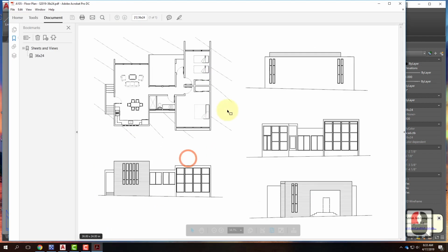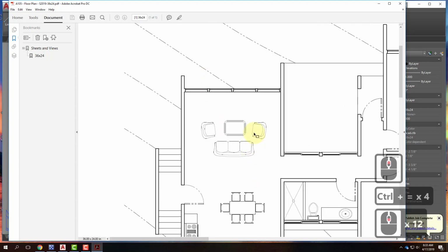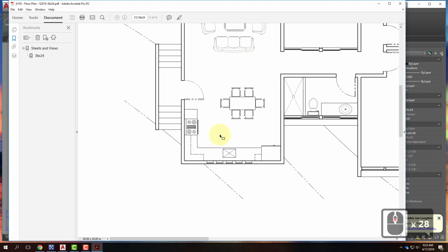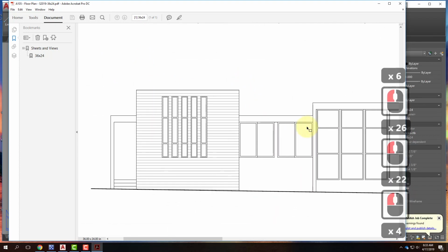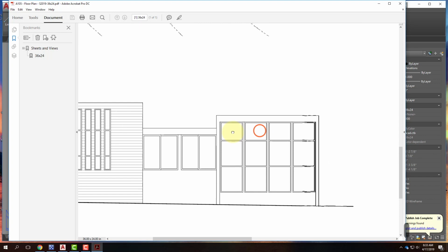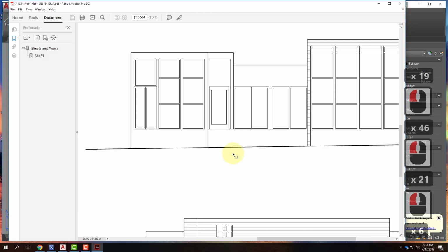So at this point, it's time to start going through and touching up my drawing. I saw in here earlier that my doors are all phantom lines, which is a mistake. My line type was incorrect, so I need to go back and correct that. I'm also seeing that some of these blocks have darker lines and lighter lines on them, so I need to correct that because they're not reading quite correctly. So you want to take kind of a look over your drawing and say what's reading correctly and what's not reading correctly, and make sure that you fix those. It looks like my elevations could use a little bit better line weights as well, because they're not reading particularly well other than the ground line itself. So I have some work to do just to kind of touch it up.